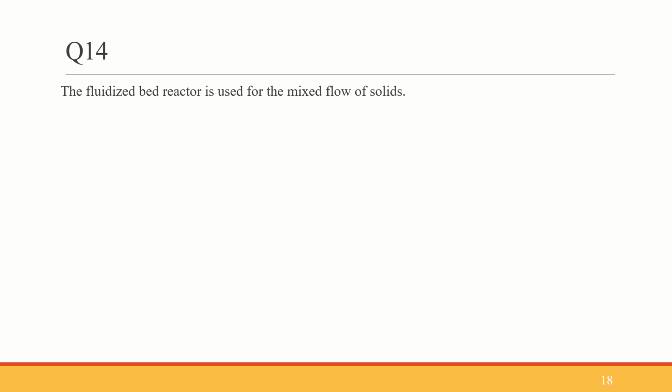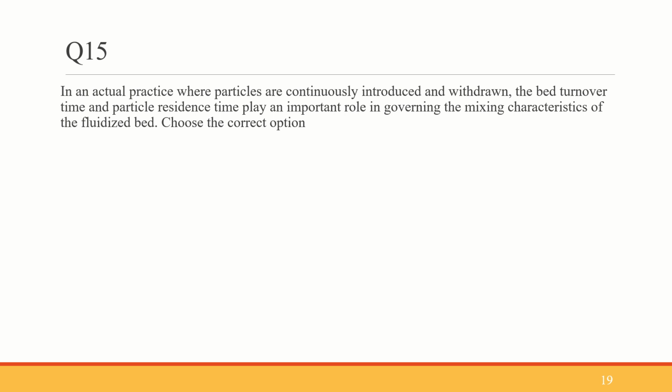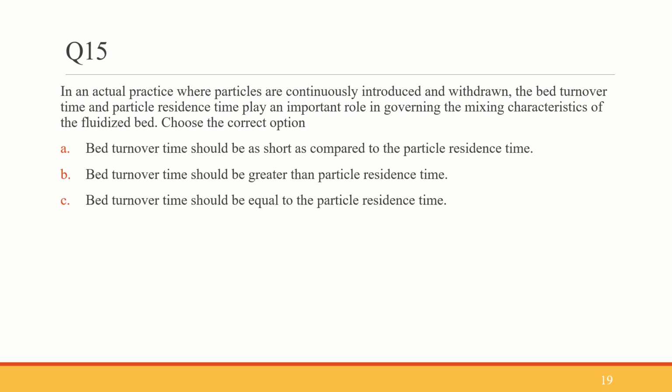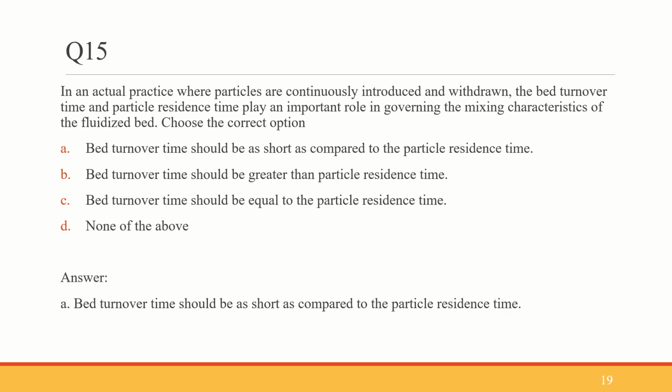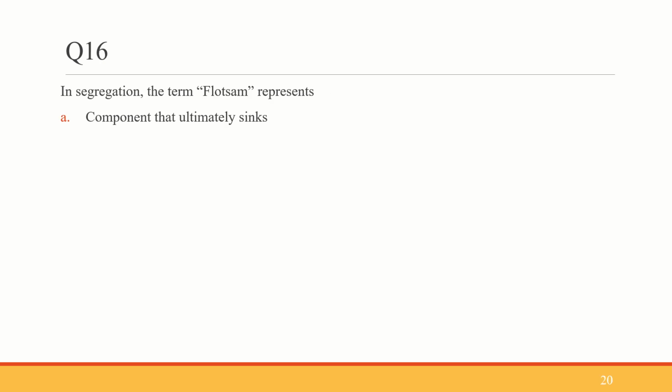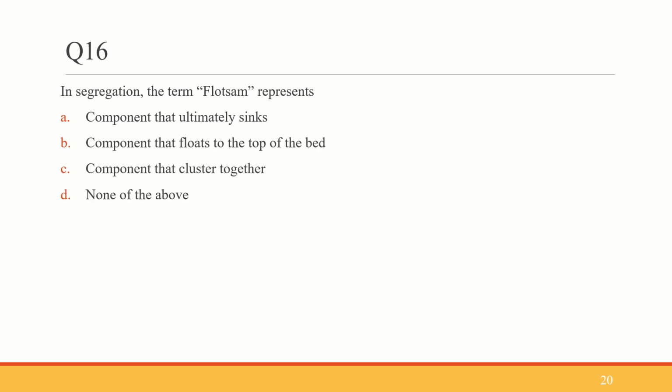It is about the fluidized bed reactor being used for mixed flow of solids. True. And in actual practice, particles are continuously introduced and withdrawn. The bed turnover and particle residence time should be as short as possible. That is a statement. Flotsam is the particle that floats to the top of the bed. Jetsam is the one that sinks to the bottom of the column.